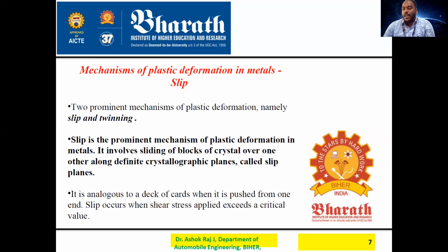It involves sliding of blocks of crystal over one another along definite crystallographic planes called slip planes. So this is one plane, and another plane is there like that. When you apply a force, what will happen? It plastically deforms, so it involves the sliding of blocks. See, this is one block, this is one block. You have to assume that arrangement. So the sliding of blocks of crystal over one another along definite crystallographic planes is generally called slip planes.